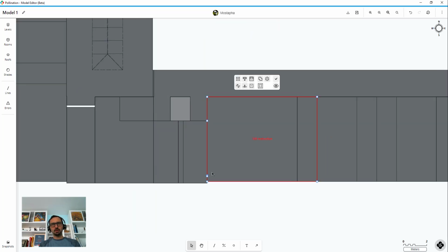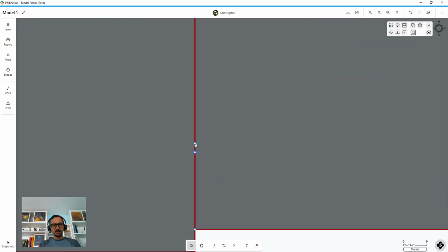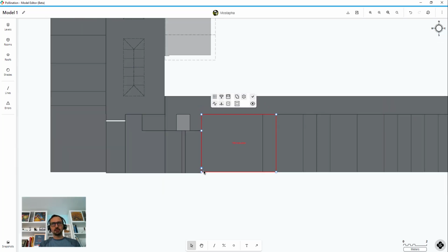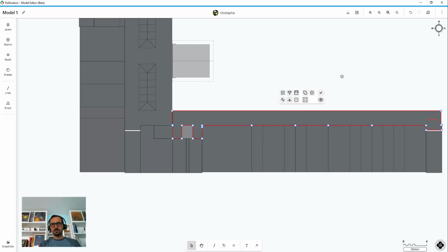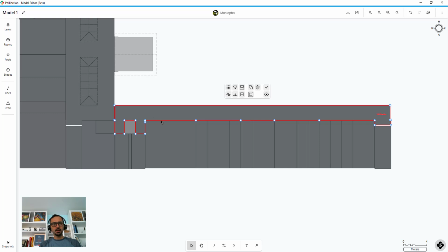When I did that remove short segments, all of them are removed, but you see all these additional vertices that are created. Or if I select this walkway, for example, the corridor, you'll see there are smaller segments. They are planar, but they have been segmented because their walls are intersecting with each other. So during the cleanup, usually you don't want them.